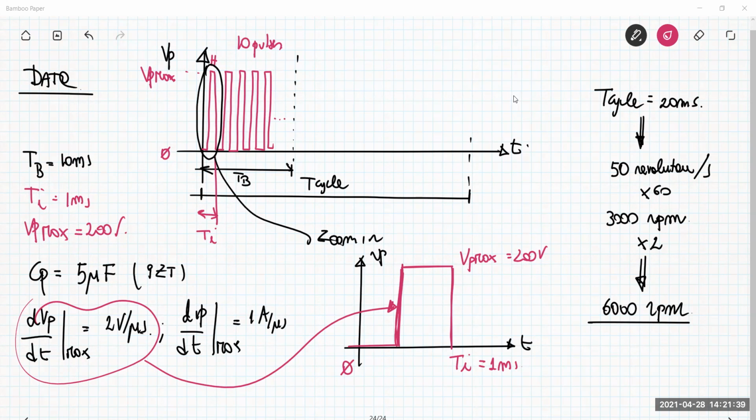Of course you have to make the system stable, so you need something in your closed loop to compensate the loop gain of my closed loop system. Typically this is done with a compensator, a transfer function which includes proportional terms, integral terms, or also derivative terms.